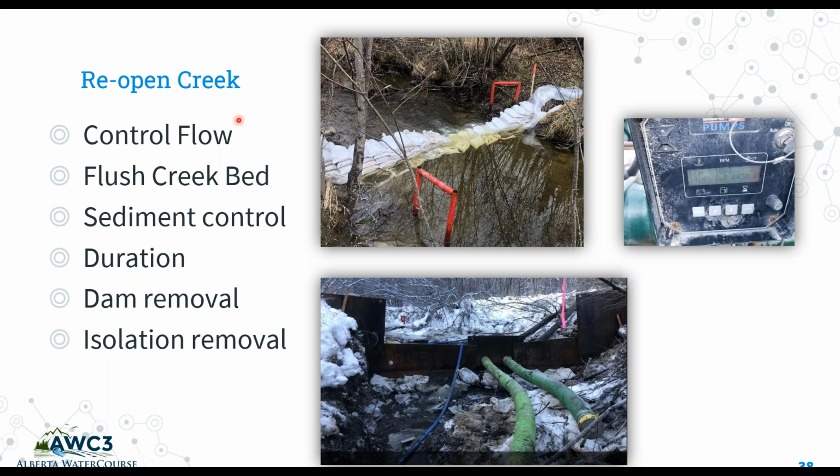Once we have excavated our creek and our restoration is complete, we are now going to reopen the creek. So reopening the creek, we have to make sure we are able to control the flow to flush the creek bed properly. We want to make sure we're able to control our sediments. This may take a couple hours, it may take a couple days.